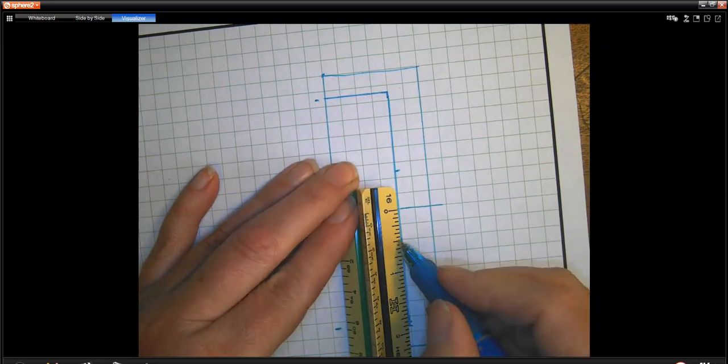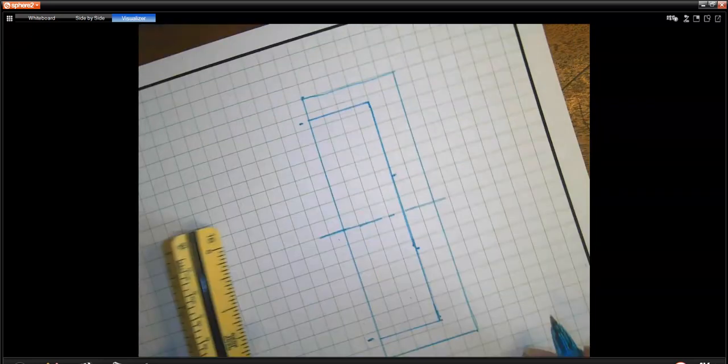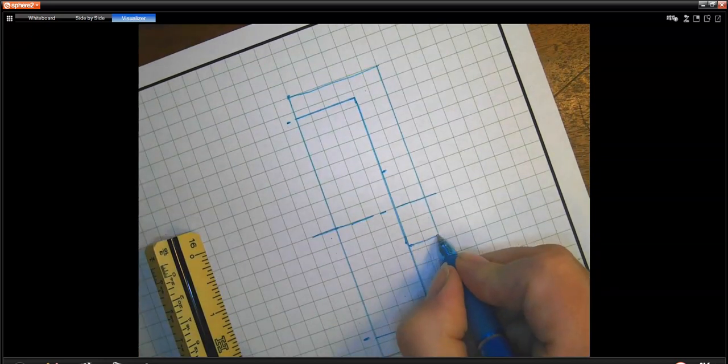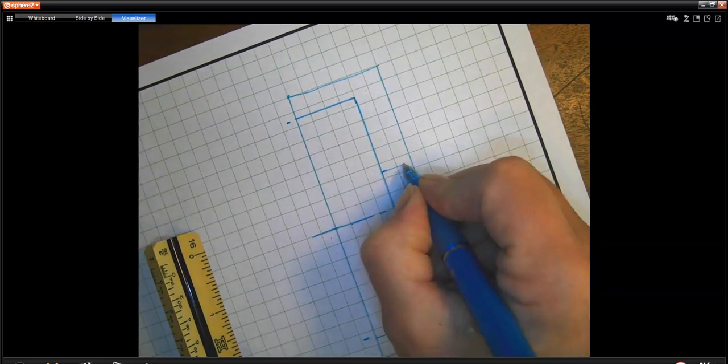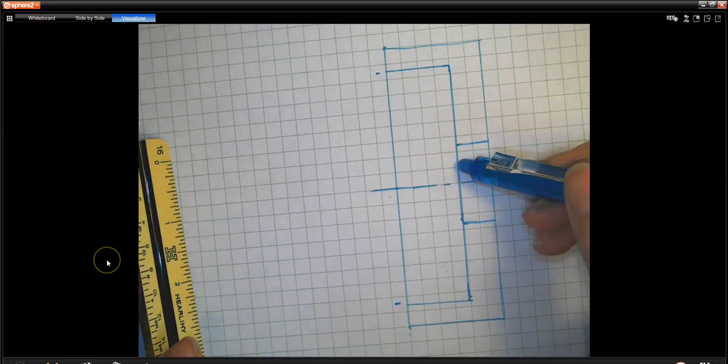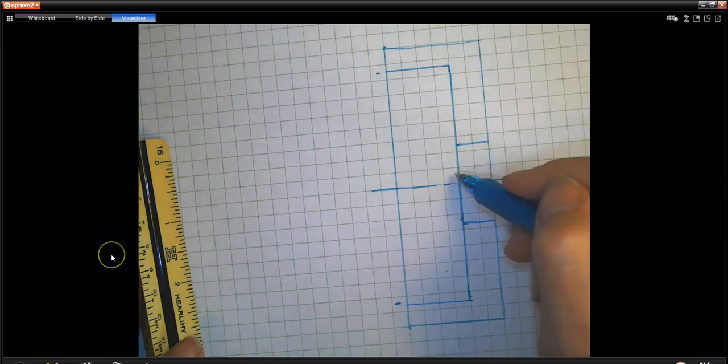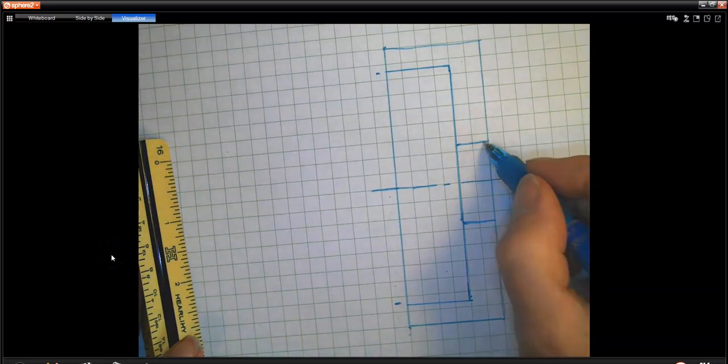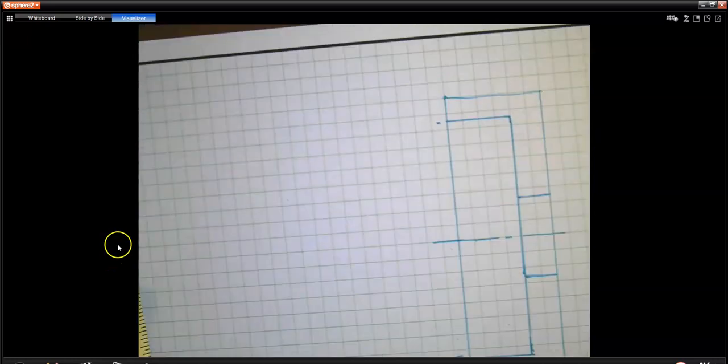And then measure down 5/8. 1, 2, 3, 4, 5 in the middle of that block. And then just put that in there as the hole. Okay, so that is representing that hole that is in that part. Now, this line will exist on the back side. That's on the back side of the cut. And this is what we have for our front view.